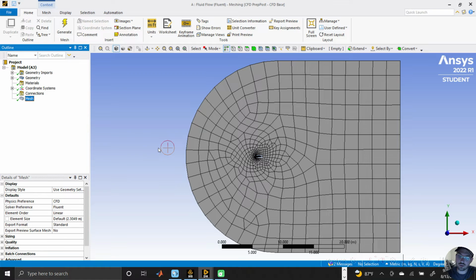Now for anyone watching who has never used ANSYS before, probably exactly like I did when I was starting out, you have no idea what you're looking at here. This is a collection of elements, that's all these squares, that make up the total of the part that we are analyzing. What each of these represents is a single data point in a string of differential equations that the ANSYS modeling software is going to use to run the simulation that we're going to be running.